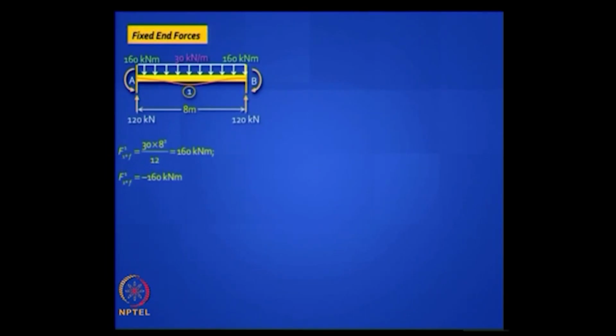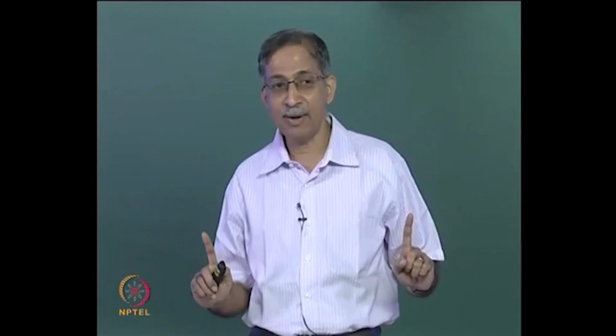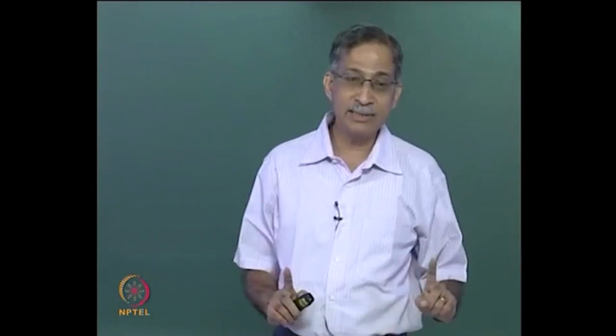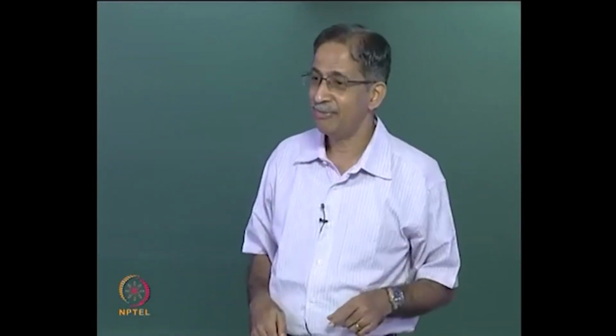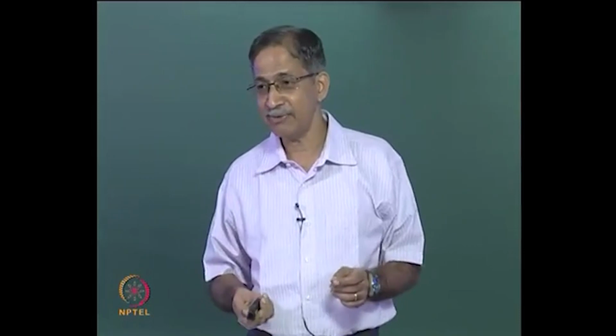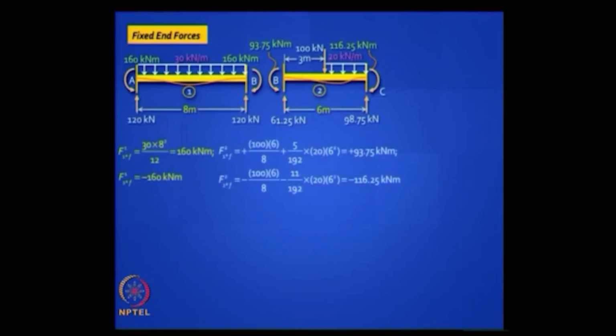Now we have to find the fixed end forces. We've done this problem earlier, so can I go fast over this? You can work out the fixed end forces. Remember, you also need to find the vertical reactions. Why do we need to do that? Not only the fixed end moments, also the vertical reactions, because in the global coordinates they pile on to those vertical forces in the coordinates you've identified. So you need to do that little extra exercise, but that's easy to do. We've done that earlier.